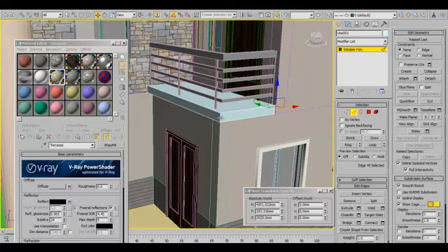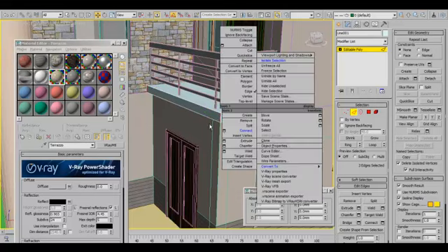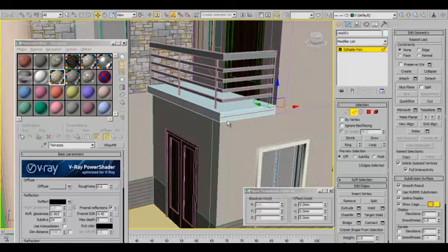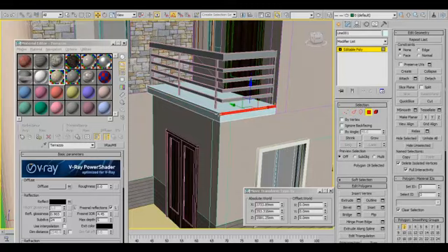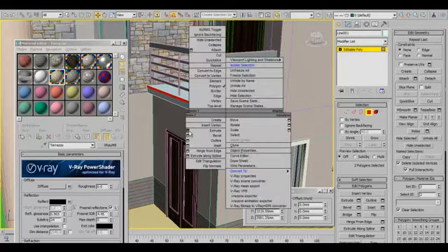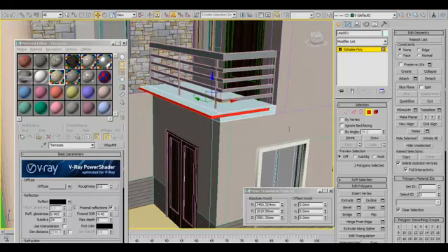And what I'm going to do now is cut a line through all these ones here by using my connect, and I'm going to offset it a little bit to go up, and I have a 50 for it, and that is good. Then I'm going to extrude this a little bit, and I'm going to use extrude local normal at 50, and I'm going to accept that.